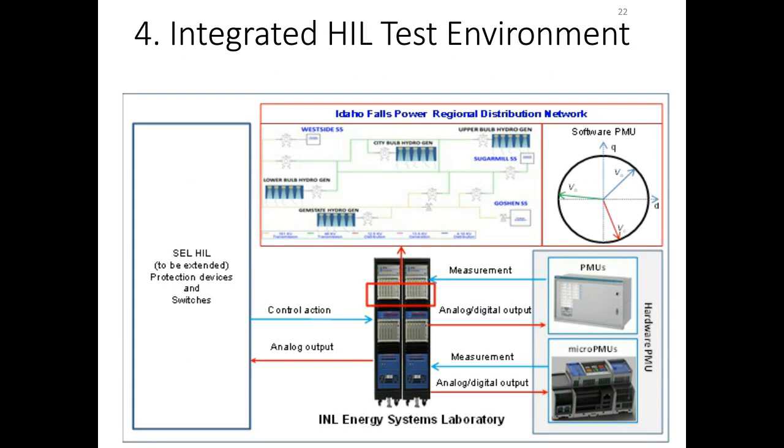It has 4 run-of-the-river plants represented on the top side, and we have the hardware in the loop of the real-time simulation, with the switcher relays hardware connected to the system, and with the micro PMUs behaving and acting as if it's the real system. This allowed us to redesign the reconfiguration and the islanding of the system using this approach.